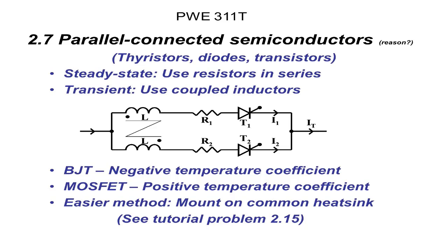So now, if I have two thyristors connected in parallel, remember, we still need to protect the switch from the di/dt. So that's why you're going to have a resistance and an inductance L attached in series with each of the switches or thyristors.